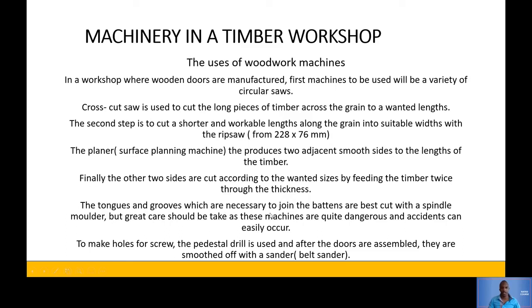The tongues and grooves, which are necessary to join the battens, are best cut with a spindle moulder, but great care should be taken. Tongues and grooves are used if you want to decorate your doors. You do certain patterns, cutting shapes deeply through the door to make it look nicer. So you would use a spindle moulder to do that. And then to make holes for screws, you use the pedestal drill, which is just a normal drill.